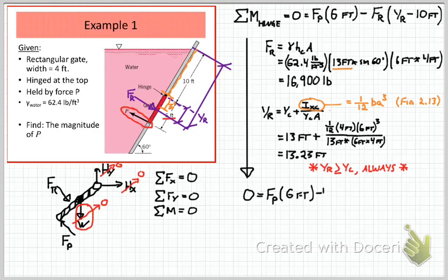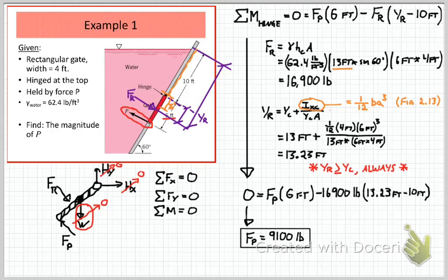Now, with both of those calculated, we can plug into our sum of the moments equation. And solving that equation, I calculate a force of P of 9,100 pounds.